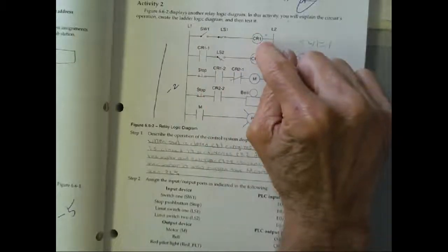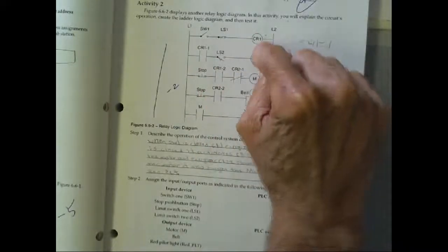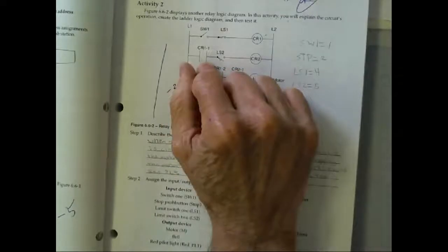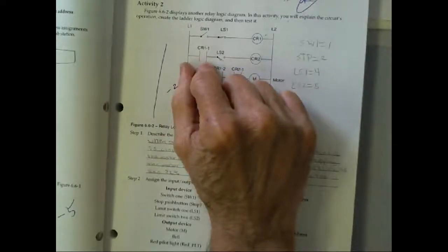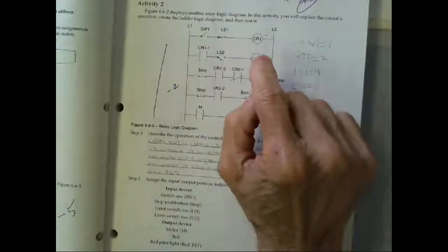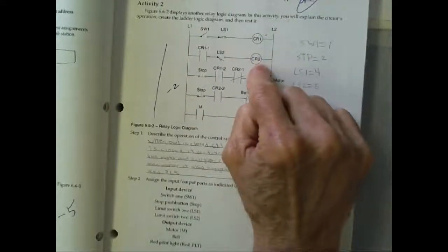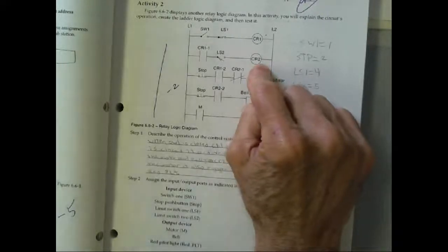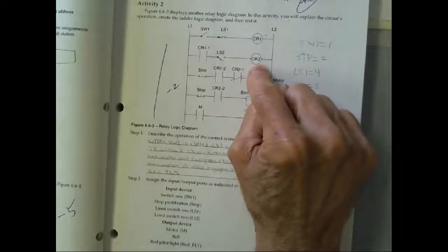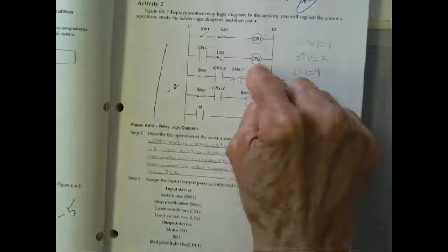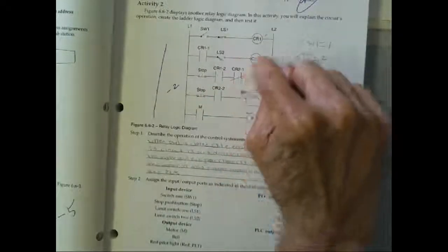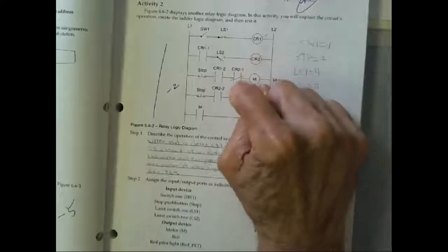then you'll use that same address here. But once you assign a symbol, guys, for this contact you don't have to know the address anymore. You just type in the symbol name, right? This will be an input. This will be another B. This might be B3 colon 0/1, and they're calling it CR2. This is a CR1 contact, so you'll use the same symbol here. This is a CR2 contact, so you'll have to give it a different symbol name.